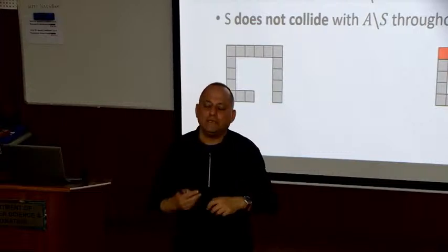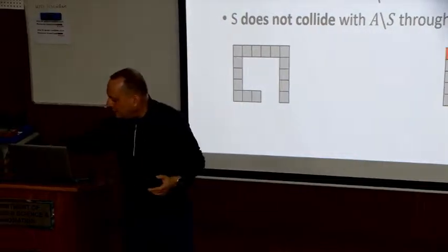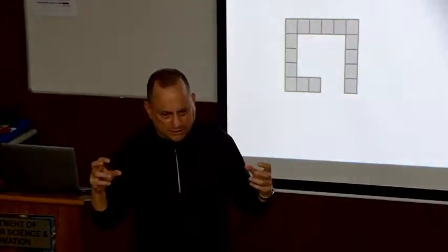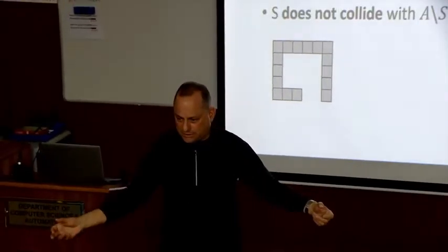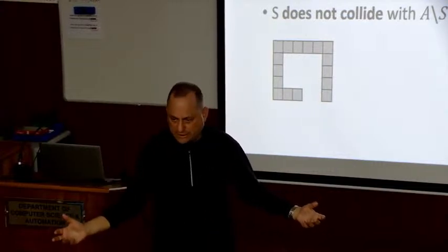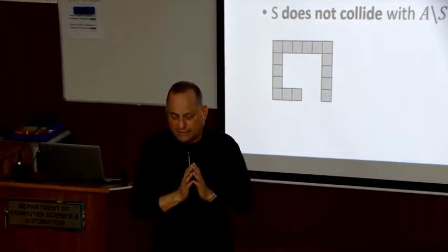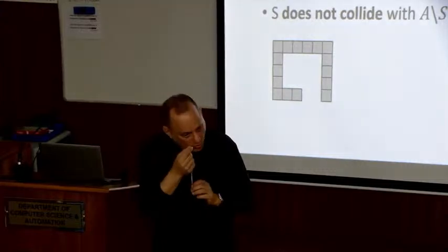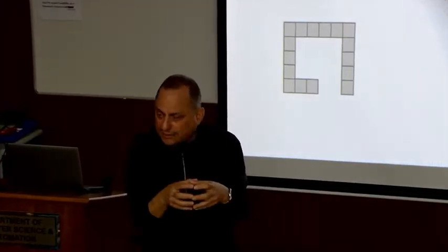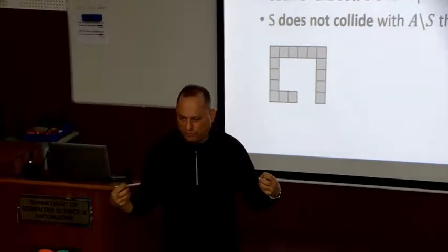What do we do? We study the problem in reverse. We start from the full product, and we try to break it into two subsets. If we succeed, we continue recursively with the two subsets until hopefully all the parts are separated. If this process has succeeded, and assuming the parts are rigid, we run it in reverse and we get an assembly plan. So a basic question here is, can I take my current assembly or sub-assembly and break it into two subsets and move them one away from the other?